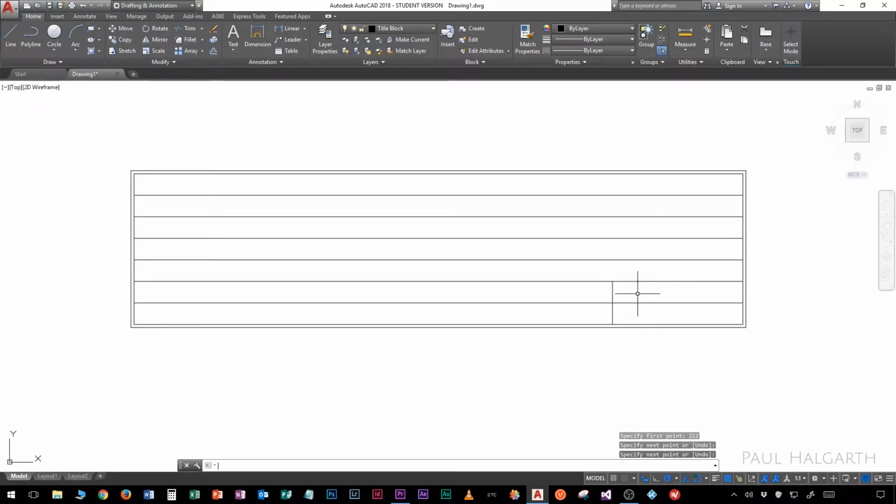Press spacebar to end and spacebar again to start the line tool. So we can see that we're 420 from this corner. So we're going to hover, wait a beat, pull across and type in 420. And this one goes up almost to the top, to there.